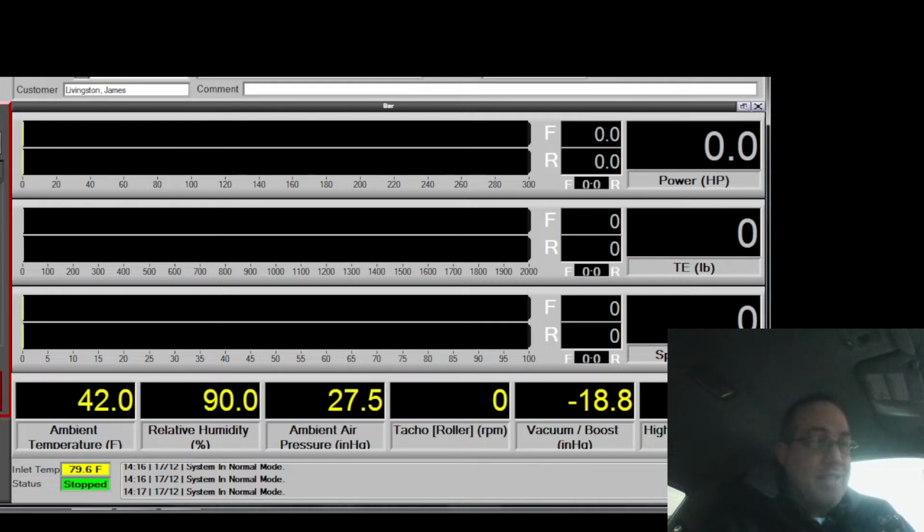Now that equation is the same for when I'm doing a weight and balance on an airplane. It's the weight that I'm putting on the airplane. It's the distance from the center. Some people do it from the center of gravity, some people do it from the nose. Depends on how it's done, but from the center of gravity, for example. So the center of gravity of the airplane is at this mark here. I'm adding 20 pounds 2 feet from it.